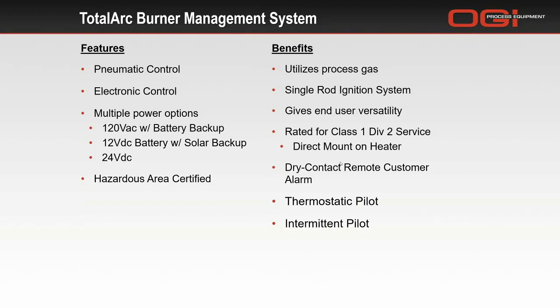Again, we use the same process gas that we operate the heater with. This system, as well as the TotalArc Relighter, both use a single rod ignition system. That means we use the ignition rod for creation of the spark plus monitoring of the flame signal. And the TotalArc BMS can be configured as a thermostatic pilot or an intermittent pilot.